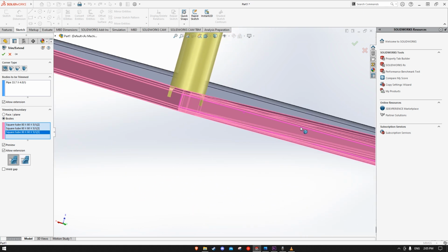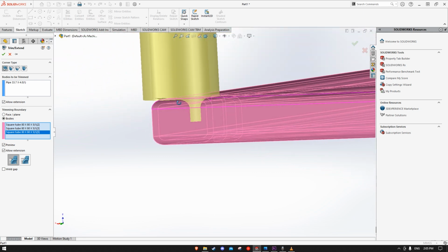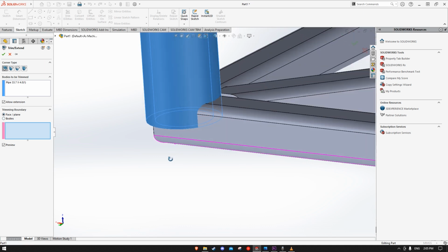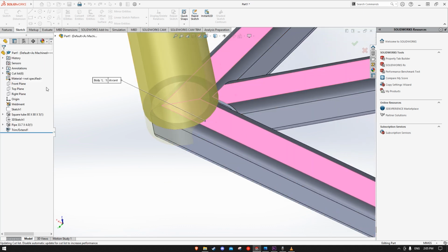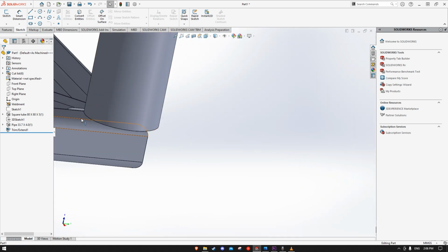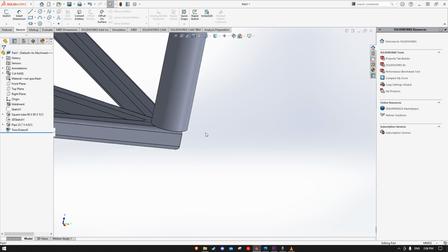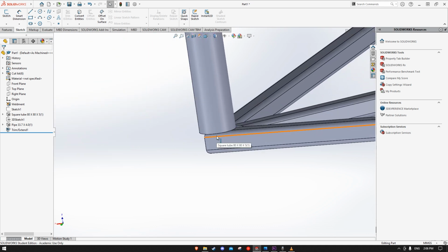As you can see, the tube is going to be molded around it and get the shape of the square tubes. But if I select face and plane and select 1, 2, and 3, click OK. Now this will cut the tube up to these faces. So depending on the situation you have, you may sometimes choose face, sometimes choose bodies. You have to work around it to understand it further. But this was just a basic example to give you a better idea.